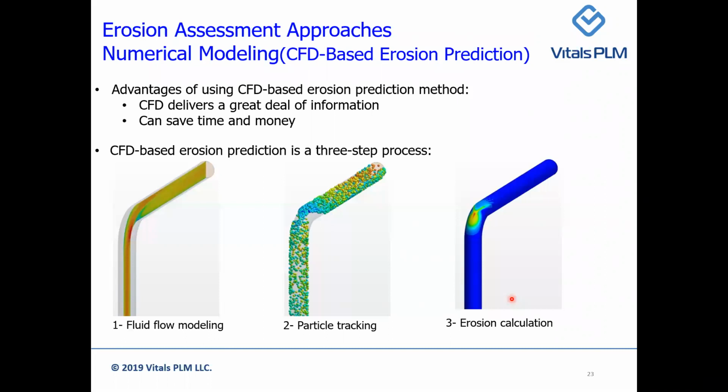In low sand concentration simulations, it is assumed that the presence of solid particles does not affect the flow. Therefore, after flow solution is done, particles are released into the flow domain from the inlet to track along the pipe. If the steady flow solver is selected, the Lagrangian solver does not need to be run until the Eulerian flow solution is converged.